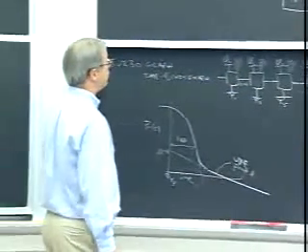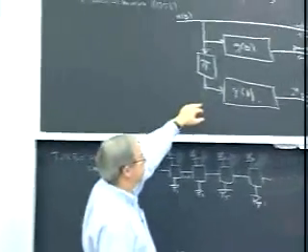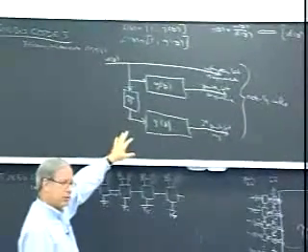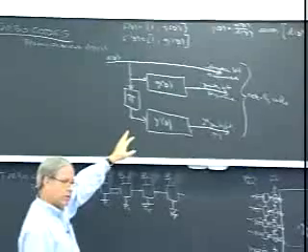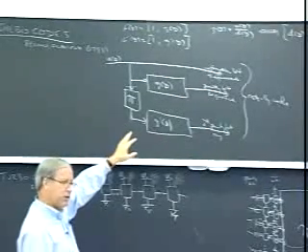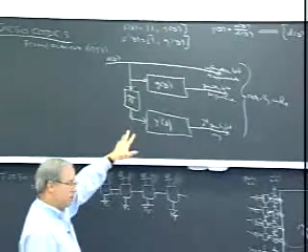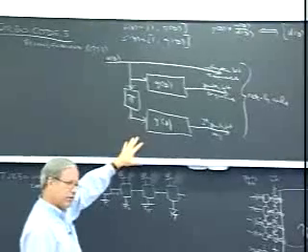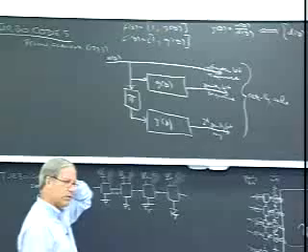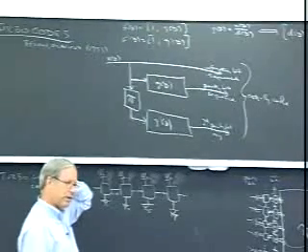You're going to disallow certain sequences, so you're not going to mess with the G of D, but you're going to go through and find all of the U of Ds that lead to low weight sequences, and you're going to expurgate them. Of course, it's a linear code, so if there's a low weight sequence in the neighborhood of 0, then there's going to be a corresponding sequence in the neighborhood of any of the code words. So you're going to have to expurgate somehow around all the code words. I don't know how to do it.